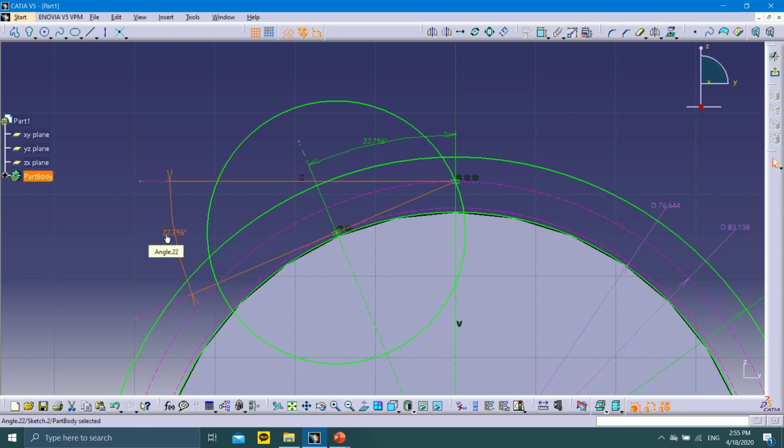This is not necessary to draw, I just give the example for you, you can delete it. The important thing is the intersection between the base diameter, if you know it, and the pressure angle. So you get this center line. But if you don't know the base diameter, you can draw a horizontal line first and then draw this line, and this circle is tangent with that line.